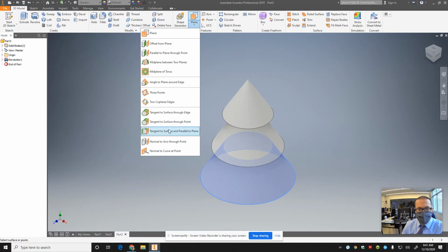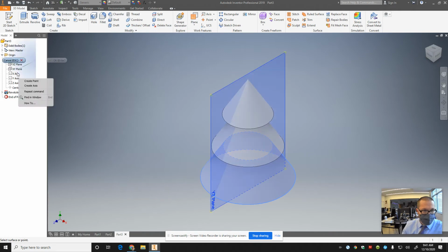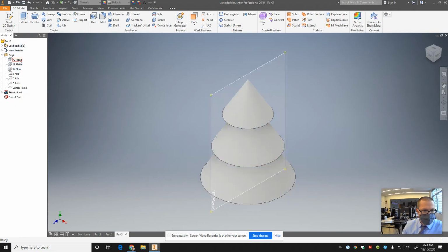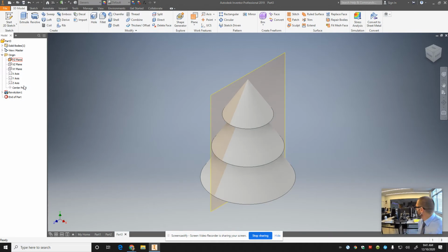So the way you do that is you find a work plane that goes through the middle of your model. All right, for instance, this one, I'm gonna make it visible. This work plane that goes through the middle of your model. So work planes, when you want to draw stuff, guys, you want to change surfaces, you really have to be able to add work planes, to add sketches, to add points and lines.